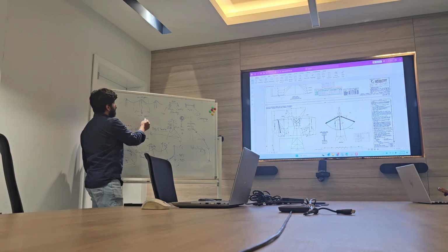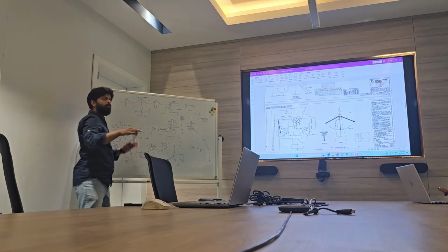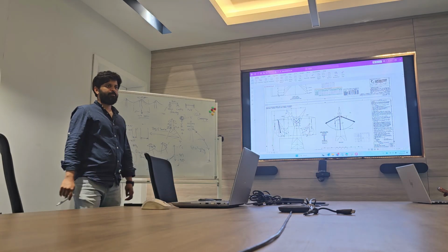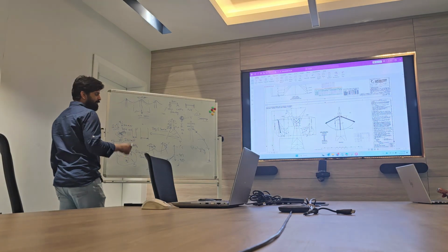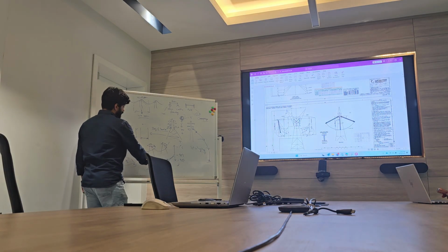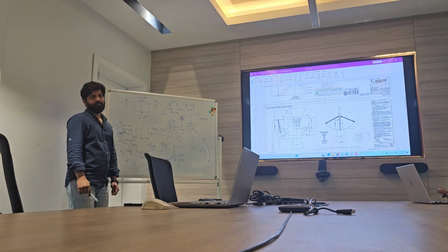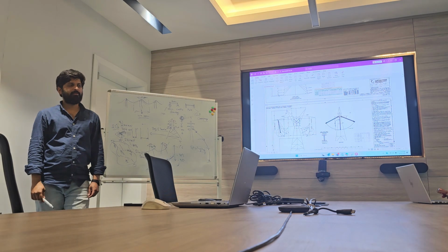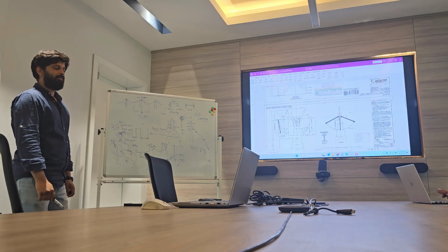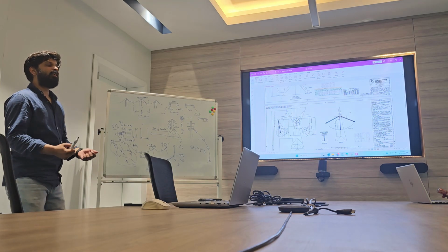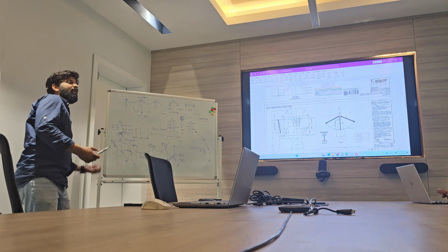But in a normal scenario, usually weight span and wind span are almost equivalent. Wind span is always half of the conductor on each side. The weight span depends on the center of gravity of the conductor where the weight will act.